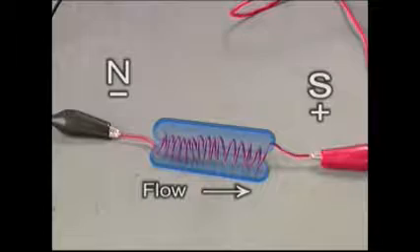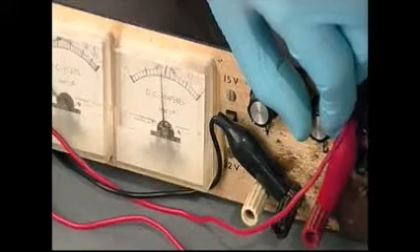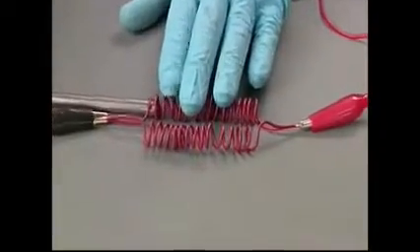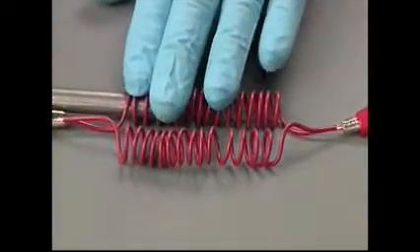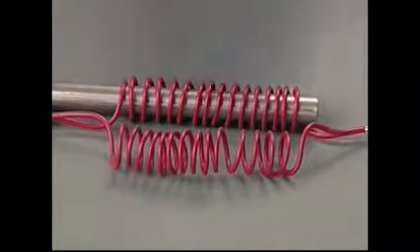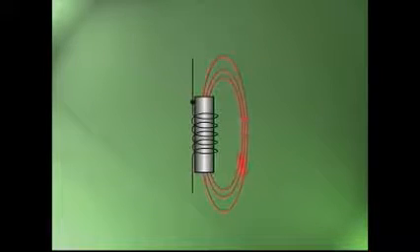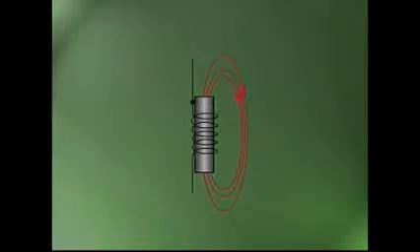The strength of the field around that coil may be increased by adding additional loops or by increasing the current flow through the coil or coils. If a soft iron bar or core is placed inside the coil, the magnetic field is greatly increased as the iron bar has less resistance to the flow of the magnetic force than air. An electromagnet, then, is the use of an iron core surrounded by a coil of wire that carries current. The product of an electromagnet is a magnetic field that is much stronger than the field created by passing current through a simple loop of wire.